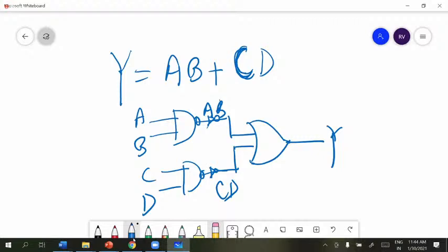When an OR gate is there, instead of putting the bubble at the back side, you put the bubble here. And when you add a bubble here, immediately you have to add one inverter here. So this I am doing externally, so nothing is changed. I have done this and this, right? So by doing this, you can understand this NOT gate and this NOT gate.